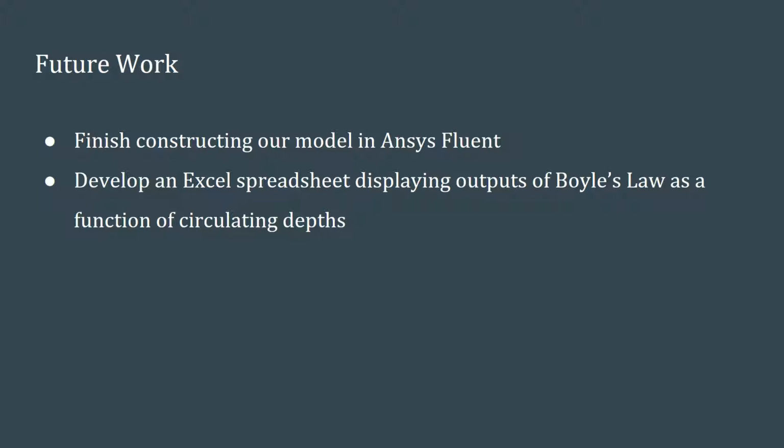Our remaining work begins with completing our working model in ANSYS Fluent. This will involve implementing a discrete gas phase that is injected into our riser mesh. We will use back calculations to predetermine a riser equilibrium point, and we'll be able to analyze the fluid behavior once this region is reached. Rapid gas expansion should be expected at this point.